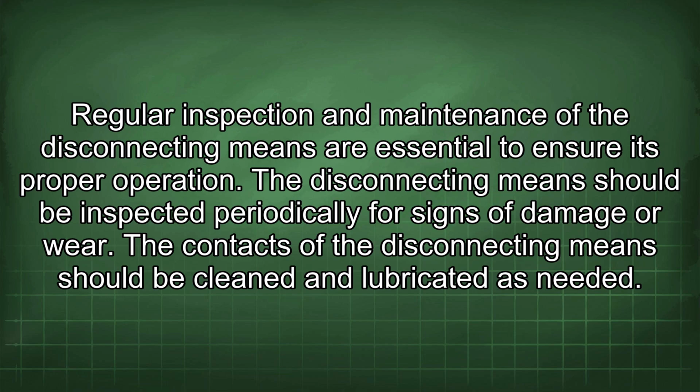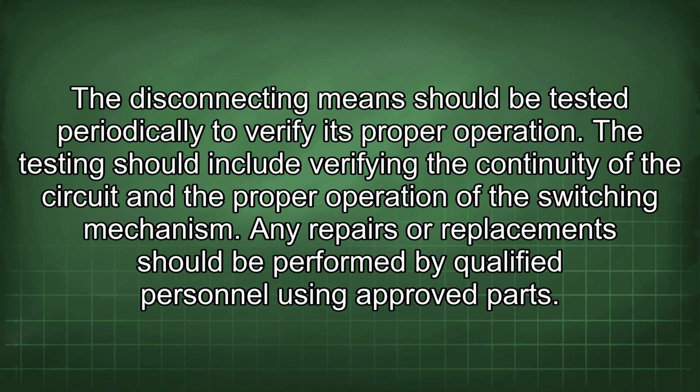The disconnecting means should be inspected periodically for signs of damage or wear. The contacts of the disconnecting means should be cleaned and lubricated as needed. The disconnecting means should be tested periodically to verify its proper operation. The testing should include verifying the continuity of the circuit and the proper operation of the switching mechanism. Any repairs or replacement should be performed by qualified personnel using approved parts.